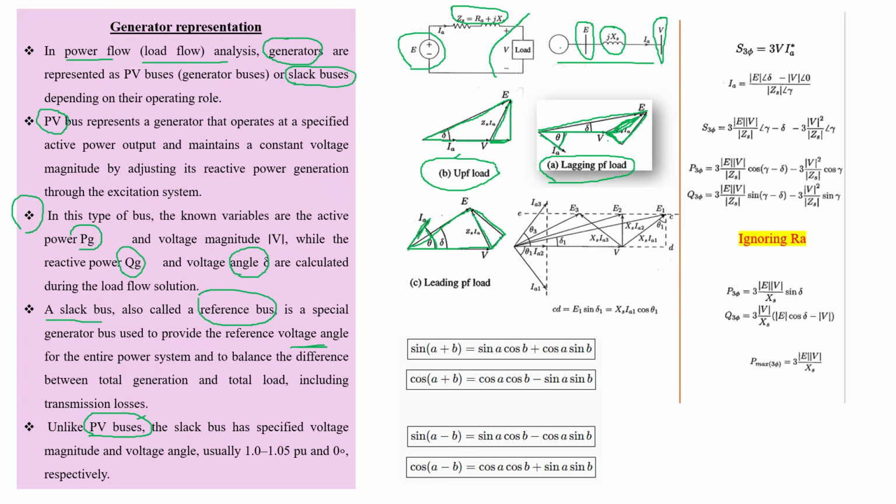So considering these three scenarios, again ignoring one reality: when we see the internal impedance of a generator, the magnitude of internal resistance is very small compared to the internal reactance. That's why we keep only the internal reactance here. So considering that, if we draw a phasor diagram of internal voltage, terminal voltage and the power factor for the three cases on the same axis, we'll have this.